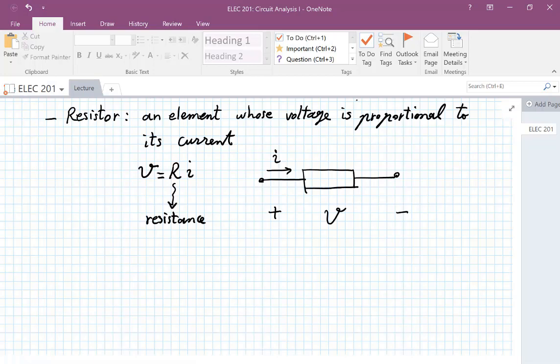Okay. Because it's a quantity that can be in either direction, we have to pick a convention, assign some direction, and be fully prepared that the value of the quantity might be negative, in which case the current is actually the other way. Okay? And we'll know that after we solve the circuit. So very, very important point number one, that when you see something like this, do not assume that that's the actual direction of current flow in the circuit.